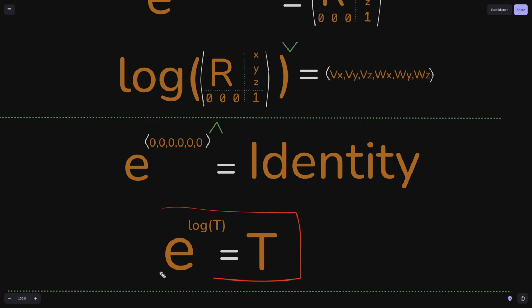Okay, this is a very good thing you should add into a unit test. You can sample the algebras, exponentiate them, and check if they generate the transformation that we're generating from it. So basically, what you can do as well is take a URDF of a robotic arm, and uniformly generate thetas of the different angles of the axes of the robotic arm.